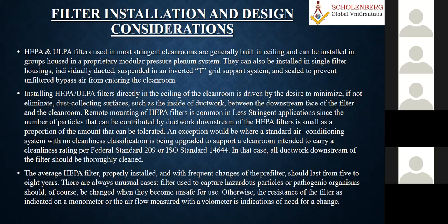For example, as I told you, the operation theater. Ideally, I want to locate HEPA filters inside the operation theater, above the operation table. But practically, it is not advisable, because patients are there and people go in every time. Though I provide so many pre-filters and fine filters, HEPA filters also need proper maintenance. The pressure difference has to be monitored, and somebody, a technician, has to go there and replace it. So for that purpose only, we always put them remote.